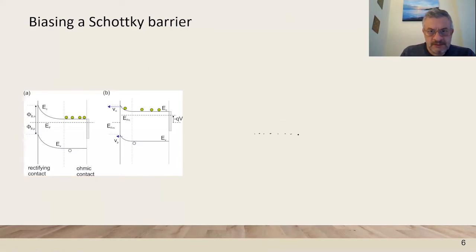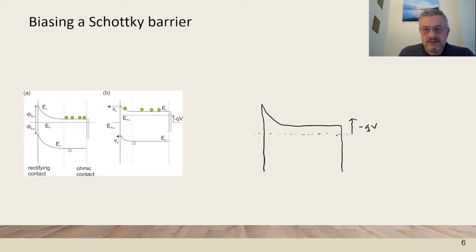So then this is the equilibrium distribution in a Schottky barrier where the voltage is zero, because there is no difference of the Fermi levels at the contacts. But now we can displace the Fermi levels by applying a voltage at one of the contacts,